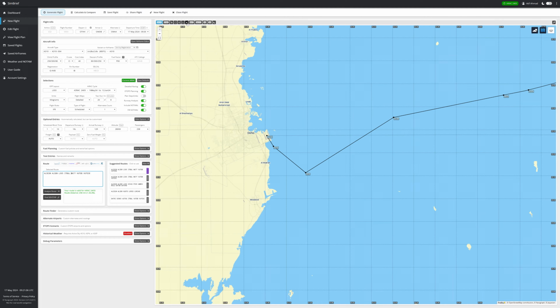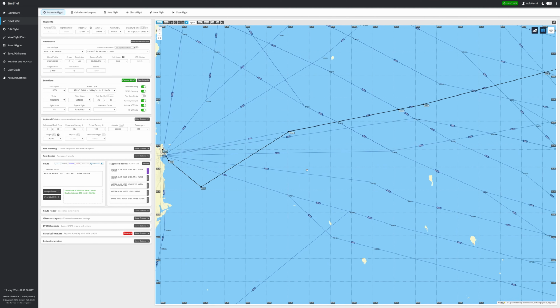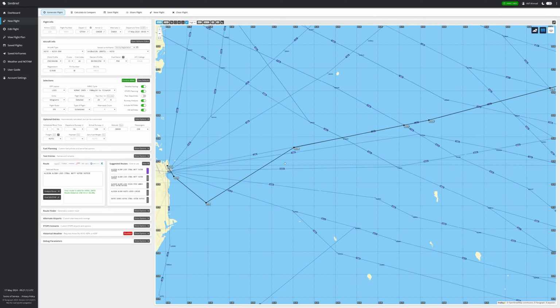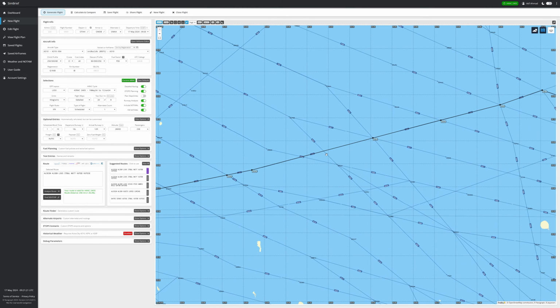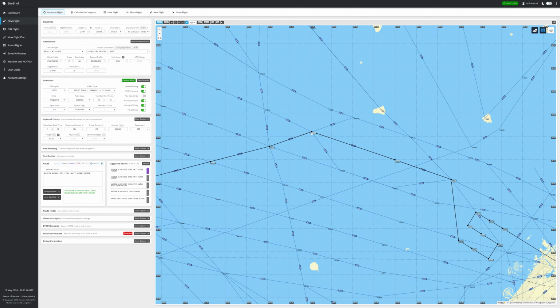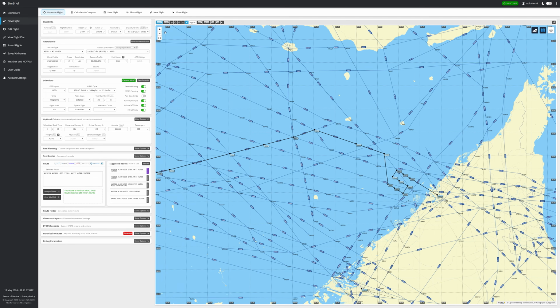If you want to look at the airways, just come over here and click this button and you will see all the airways. So after the departure, you will see this airway is being taken by the flight, L305, which will take you from LSIM, and it will take you to ITBUL. So that's how you read it. You can see this airway has taken you over here, and then you take another airway which takes you to VUTEB, and then there is an arrival procedure. So these are the airways and the waypoints.